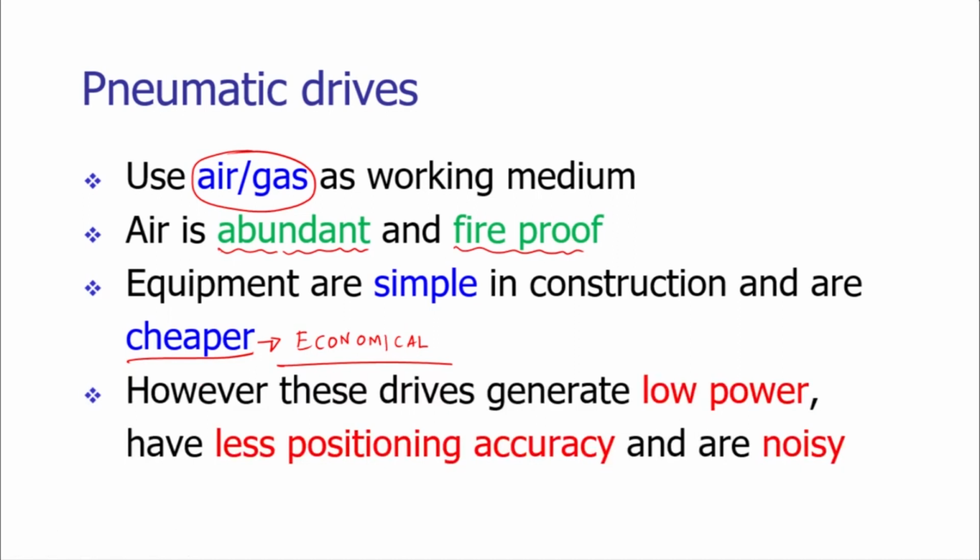But these drives do have certain limitations. These drives are generating low power. Therefore, we cannot use pneumatic drives for the transformation operations, for metal cutting operation. We are using the pneumatic drives for the auxiliary operation, say tool changing, for cleaning or the sensing operation.